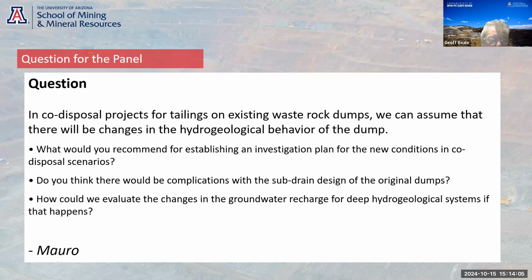So again, firstly you've got to understand the dump. Put in piezometers if you can, put in vibrating wires or standpipes, and multi-level standpipes may be the way to go, because you can sample them as well. An issue is that many dumps are layered, and many dumps have old running surfaces which allow perched water to accumulate, and there have been a number of dump failures on intermediate lifts caused by perched water on old truck running surfaces.